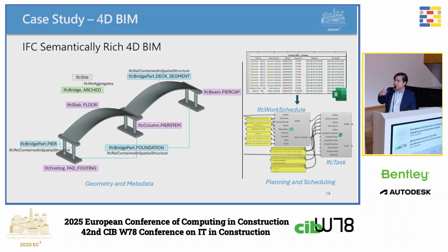Regarding geometry and metadata, the slabs of the deck were generated using IFC Advanced BREP, and each of the elements has a volume associated. For the metadata, each of the IFC elements is classified within the predefined types of the IFC schema. For planning and scheduling, we had a detailed schedule in an Excel file. We imported this data into Grasshopper and generated a work schedule and multiple IFC tasks linked to the corresponding IFC elements.